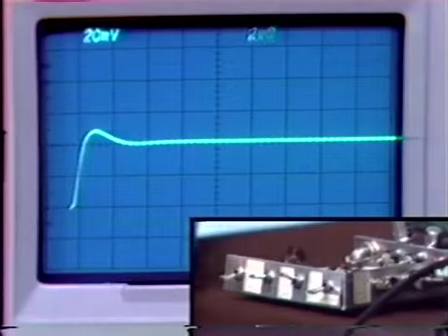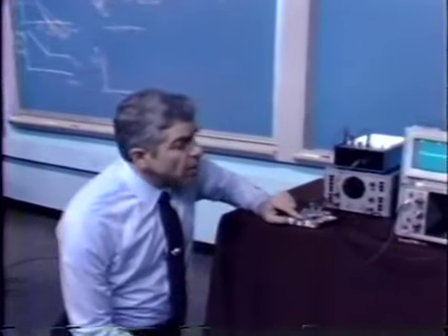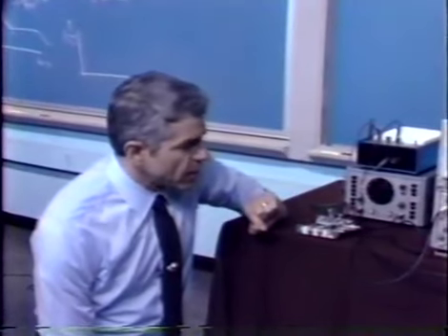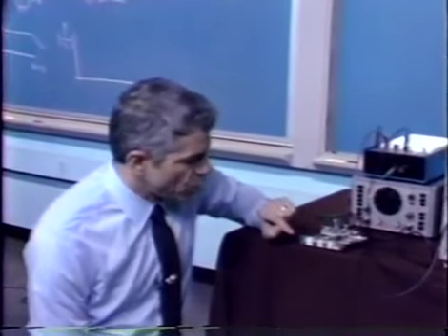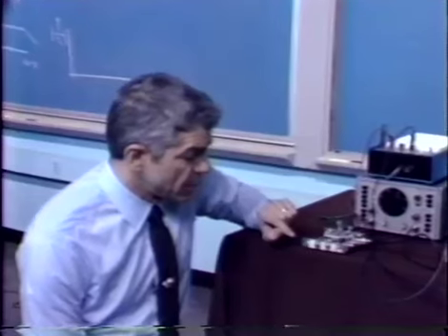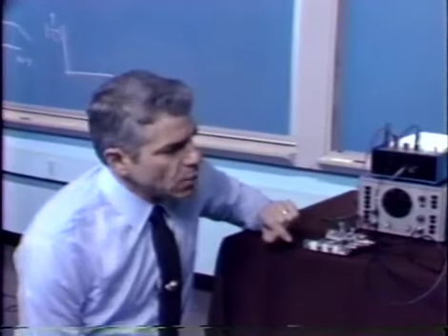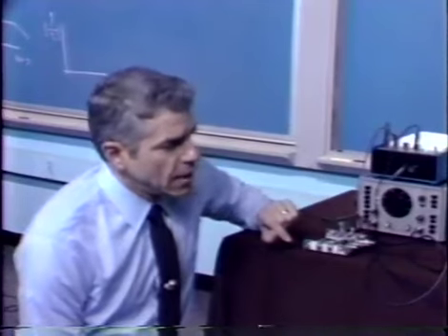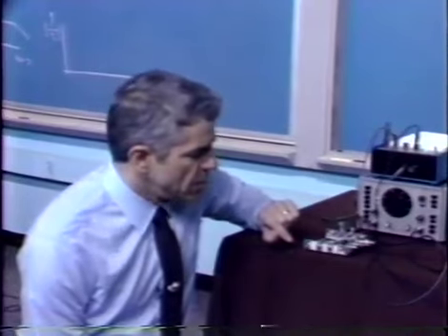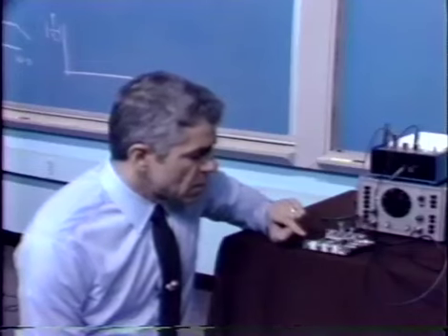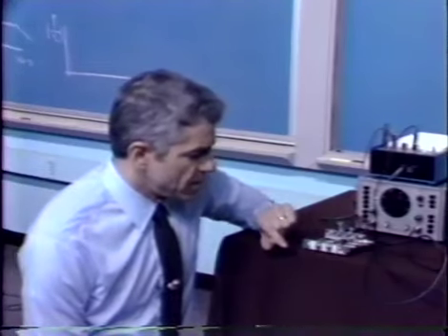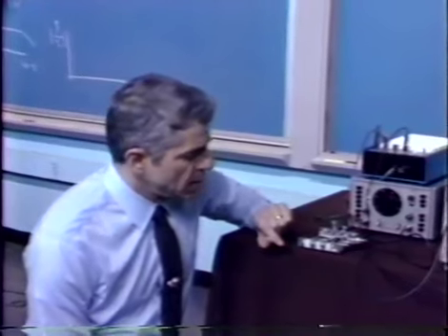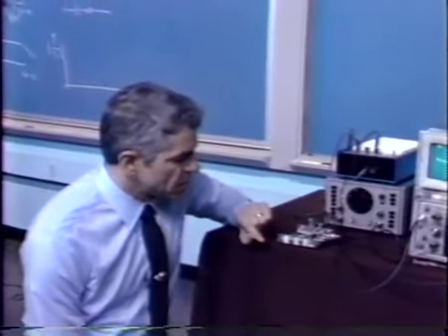What's the difficulty with this kind of compensation? Well, one of the things is it's very, very special purpose. We have already looked at 1 over s squared compensation and found out that it was somewhat special purpose. Here we're tailoring compensation to a specific load, in particular a capacitive load, and we're choosing the zero associated with this form of compensation to bear some relationship to the pole caused by the capacitive load.